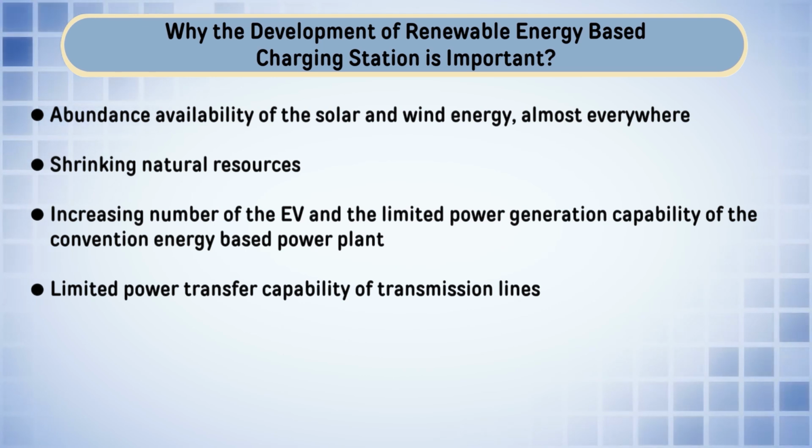If we are going for integration of renewable energy sources, we have to change the power infrastructure, because the power transfer will be both ways. If there is a small number of EVs at the charging station, we can inject renewable power. If generation is more than the load demand, we can inject the extra power into the electricity grid. Whenever the renewable generation is down, we can take power from the electricity grid to fulfill the load demand.